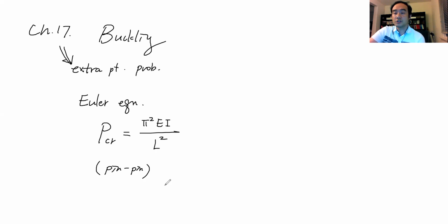I didn't cover the later sections this time, but if you're civil engineering students, we're going to talk about this buckling failure in EGR 352 in the steel design class. In that case, when we have different boundary conditions, we're going to use another factor called the effective length factor K. So the equation is a little bit different. Instead of just L, it's going to be KL, and then we have a different K depending on the different boundary conditions.